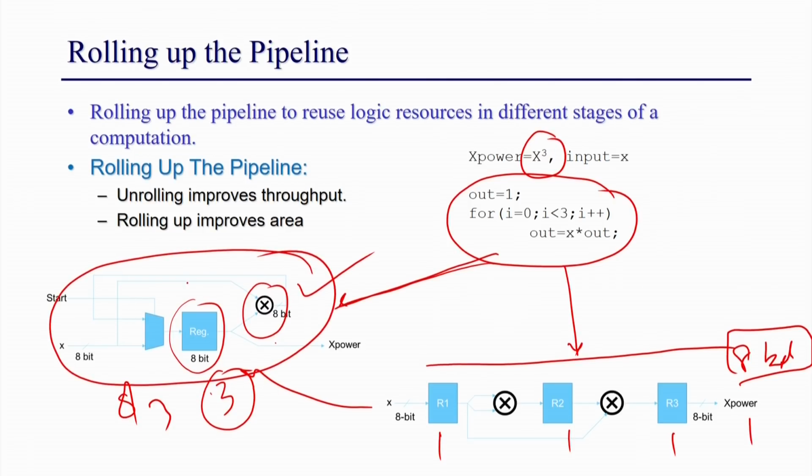Okay. So, this is what is called pipelining. So, if you have a pipeline design and really care about your area, your design is very big, and even saving these 2 multipliers is useful, you can probably do this implementation instead of this, right. But again, if you do this, you need some other synchronization like a finish signal, because now it will take 3 cycles.